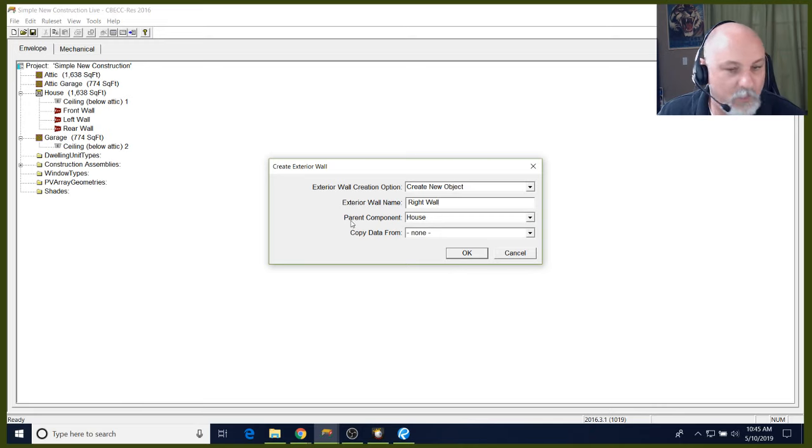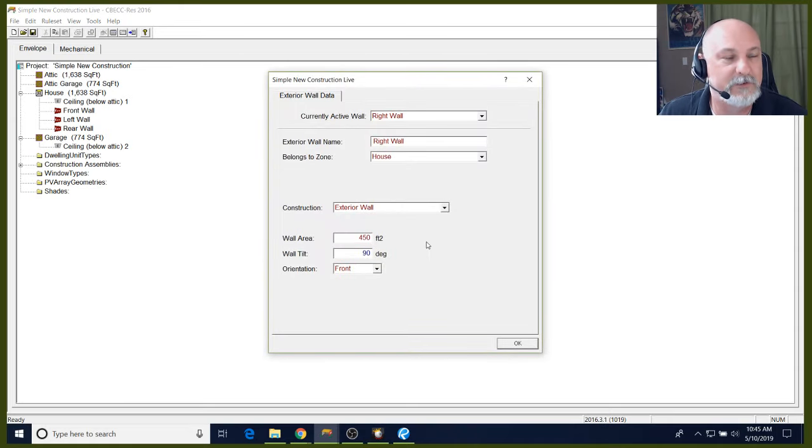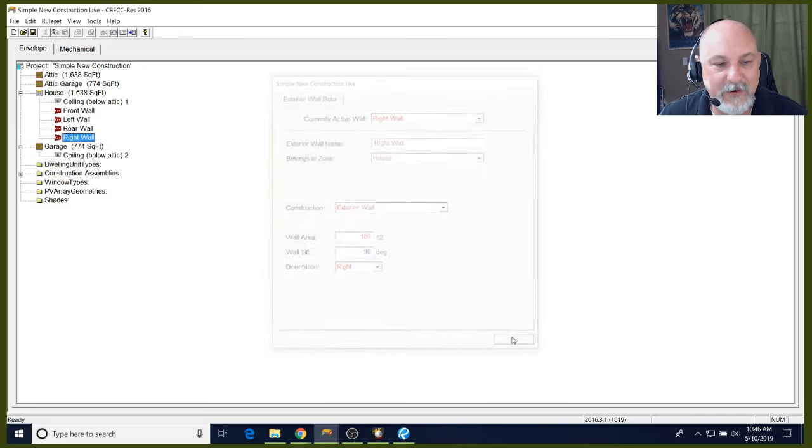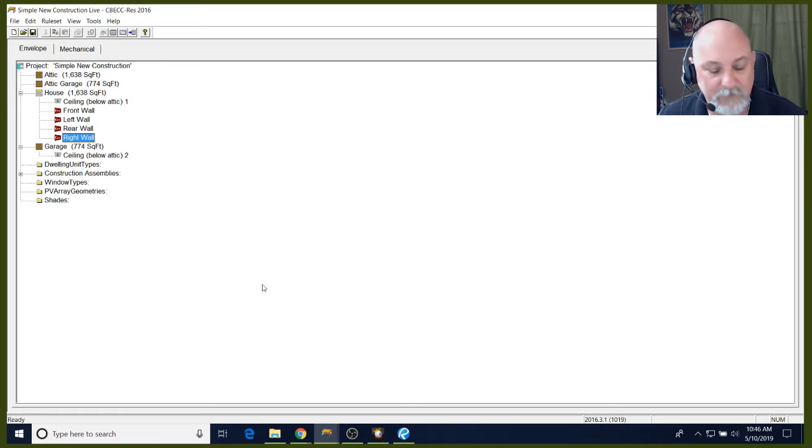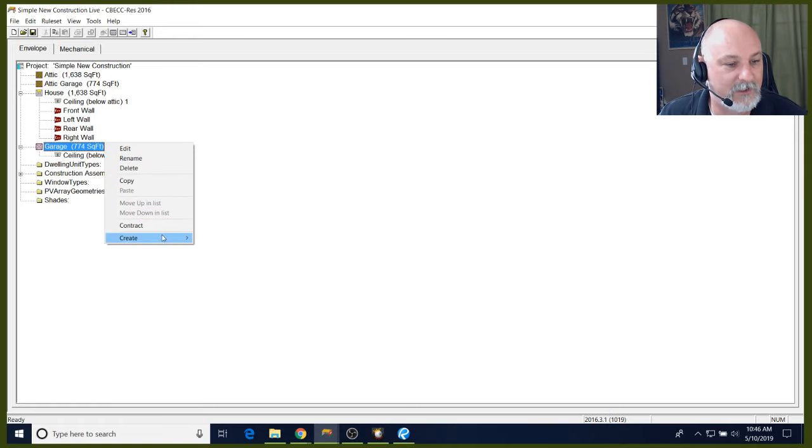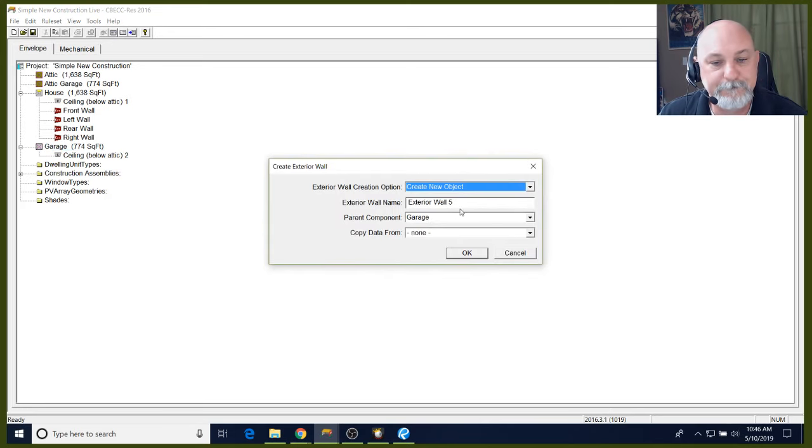Kevin says, what are your thoughts on 24 inches on center? I think 24 inch on center framing is great. There are some advanced wall framing practices. One of the issues there is you just want to make sure your client realizes that that's what you used, because their framers may just be blasting through 16-inch on center, and there's a little extra thought that needs to go into 24 inches on center framing. Like, hey, I need to align that framing under a rafter or under a truss or floor joist. So just keep that in mind.